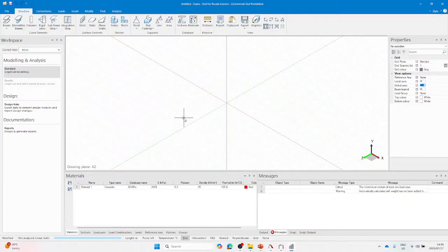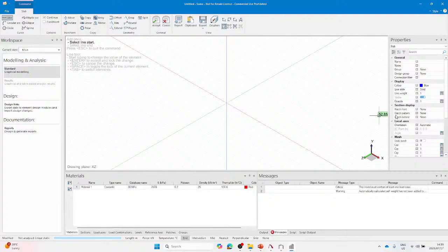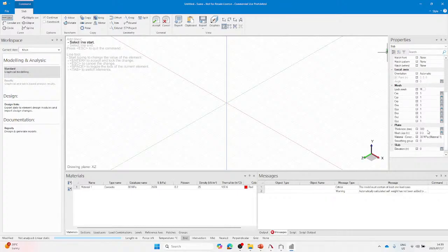And then from there we will start under the structures tab and surface. We will definitely select that we do want to add in our slab. And if we move to the right hand side where we have our properties palette, we can definitely edit those before we can place our slab in our modeling space.